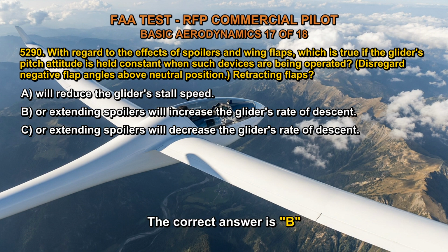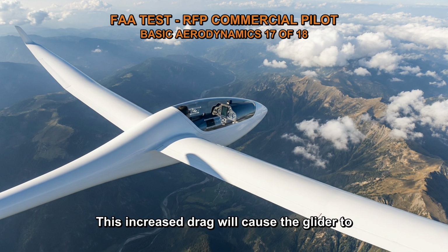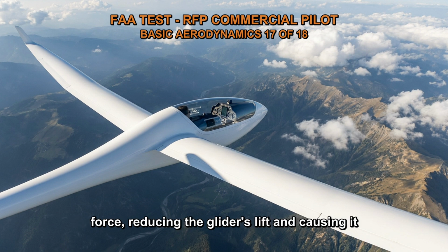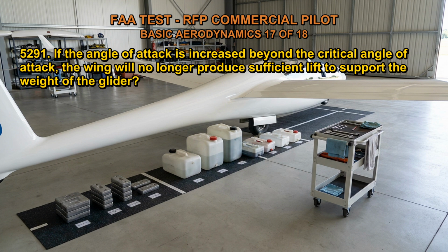The correct answer is B. When spoilers are extended or flaps are retracted, they increase the drag on the glider's wings. This increased drag will cause the glider to descend at a steeper rate for a given pitch attitude. Essentially, the increased drag acts as a braking force, reducing the glider's lift and causing it to descend more quickly. Therefore, when the pitch attitude is held constant, extending spoilers or retracting flaps will increase the glider's rate of descent.